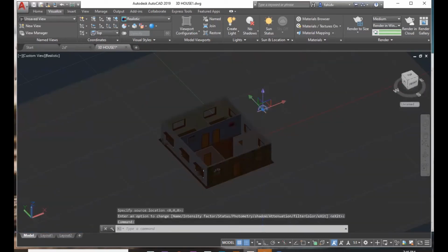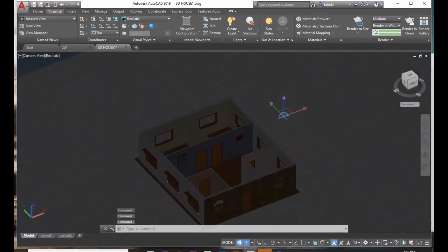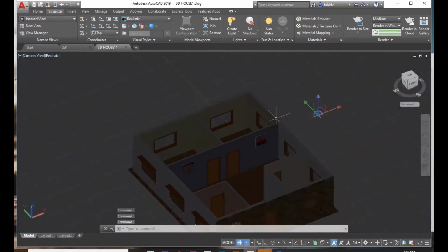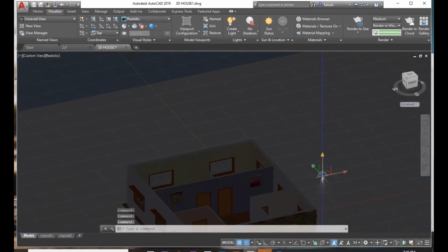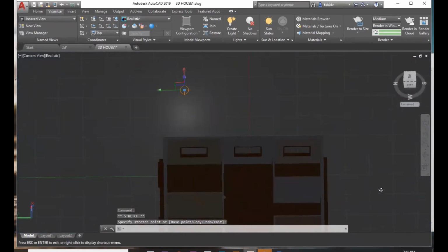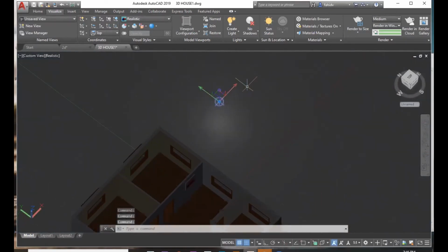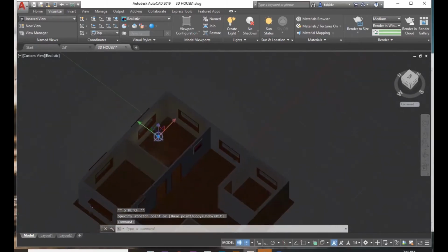Then you select it. Why I'm telling this is because it may go inside here and there. That's why I told you to keep it outside. Then I'm going to keep it a little bit up like this. Then you can go to this arrow. When you're moving this arrow, click on the end only, this arrow mark, and move straight here without switching on ortho. I'm just doing this.